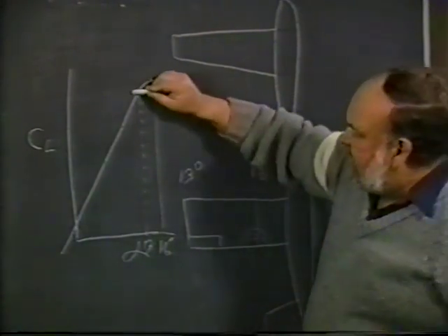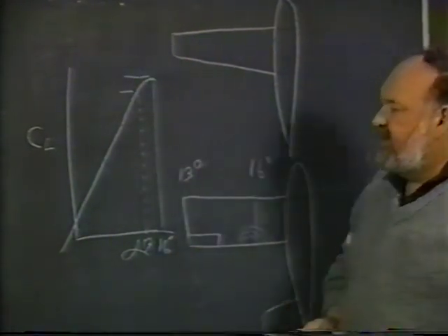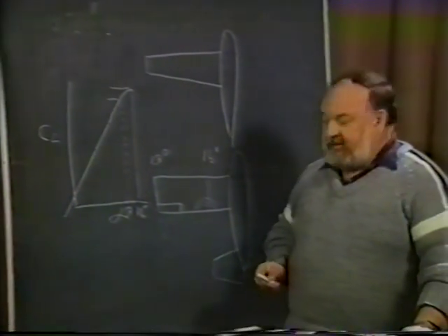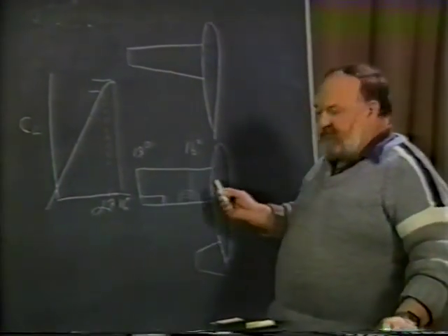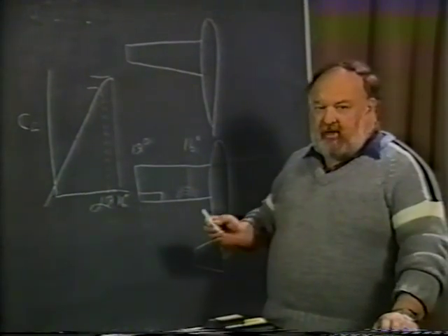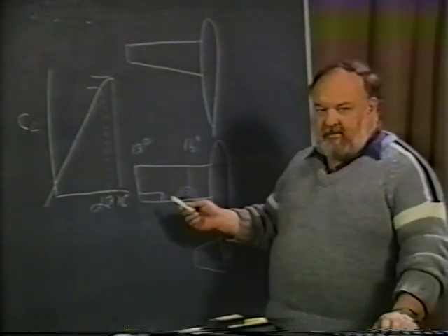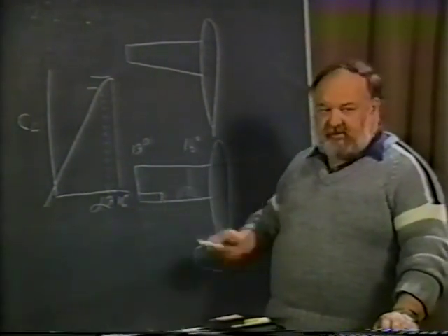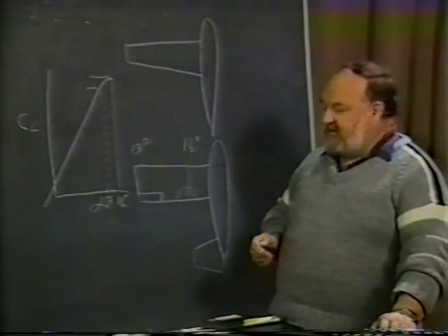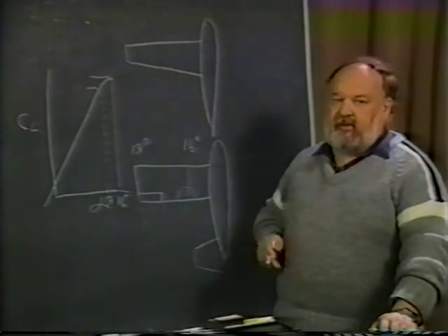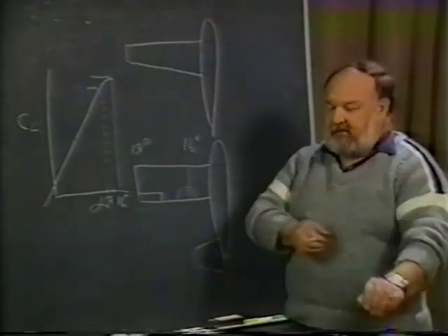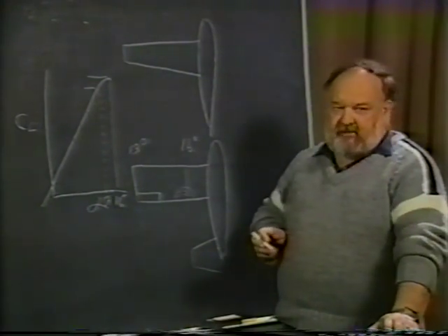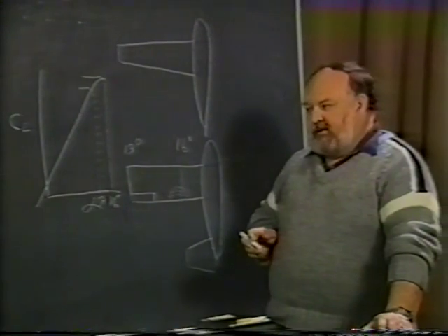you can see that there is a reasonable portion of maximum CL that this outboard section isn't going to ever be able to generate. So for that amount of area and for that airfoil section, you're not getting all of the lift that you possibly can. It may not be too far away from maximum, but it still is a factor, and it depends on how much twist you put on. The second disadvantage, of course, is that once you're cruising, once you're flying along at high speeds, particularly for a high-speed airplane, the outboard section now may not be lifting. In fact, it could even be lifting downward.